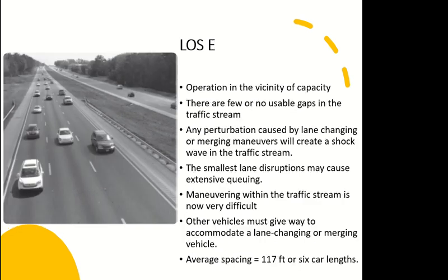Then level of service E, which is defined as capacity. You are almost at the maximum flow you can have, but this is complete saturation. So this is not stable, as I told you. Somebody is going and looking at the map, and he slows down for a couple of seconds because he wants to decide whether to change the lane or not. Even this will create a queue.